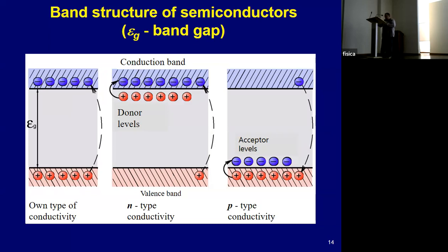After some time, an equilibrium state is established in which the resultant fluxes of electrons and holes are equal to zero. Under these conditions, a region is created in the semiconductor where the electrical resistance increases sharply and the electrical conductivity drops. This region with a low concentration of charge carriers is created. This region of the semiconductor, where the type of conductivity changes, for example, from electron to hole, or conversely, from hole to electron, is called the transition region.